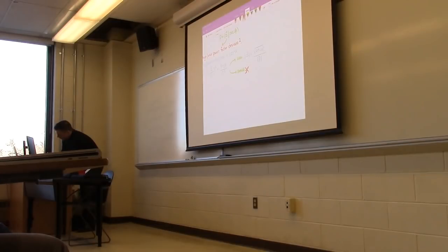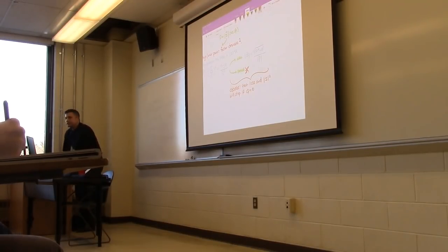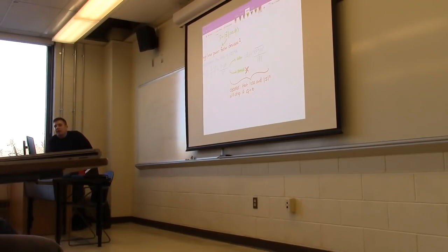The main takeaway from this is that loss and I squared, both will drop if Q is equal to 0. So that's the whole objective behind power factor correction.